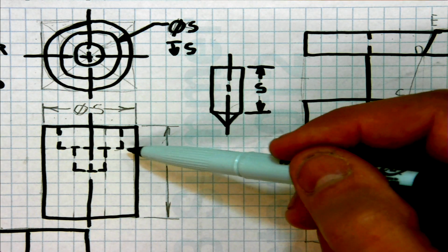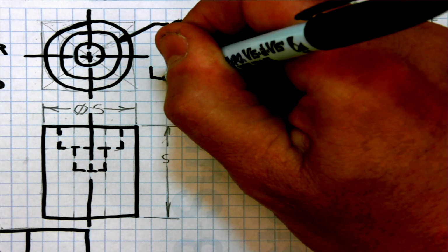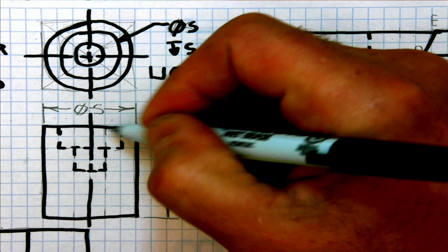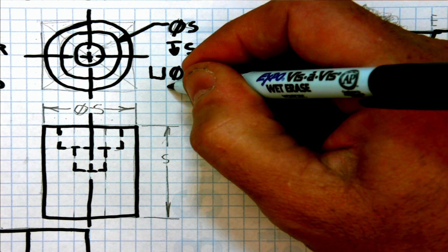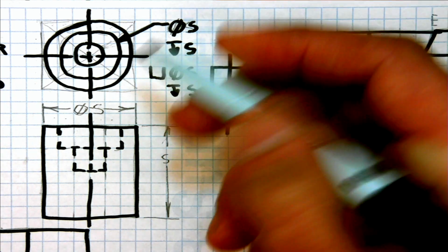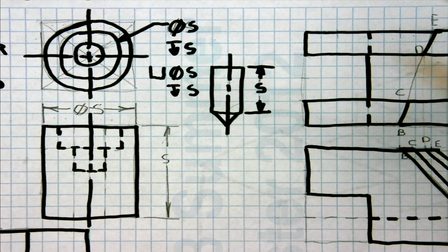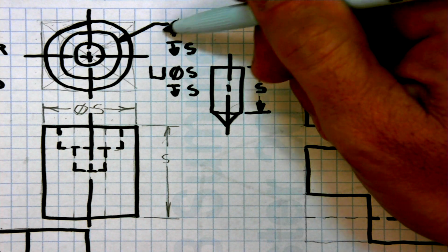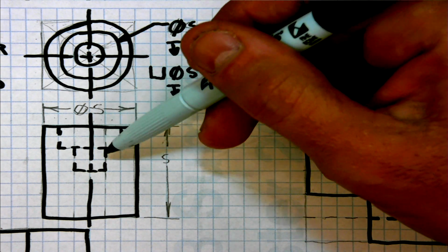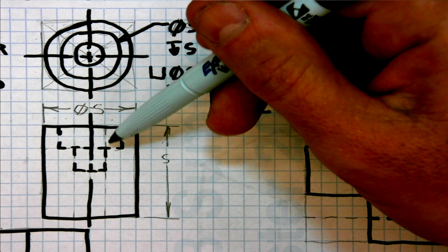But now we've made another negative cylinder in here. And now that's going to be called a U for counterbore diameter of size. That's your diameter right here. And then you have to give it a depth of size. So now you size this cylinder. There's your diameter. In this case, the depth was 2. Okay? So basically, this is the whole annotation. I kind of got it spread out, but it'd be first hole is a small one, diameter size goes down 4. Then the U for counterbore is here. Diameter size goes down, in this case, 2.